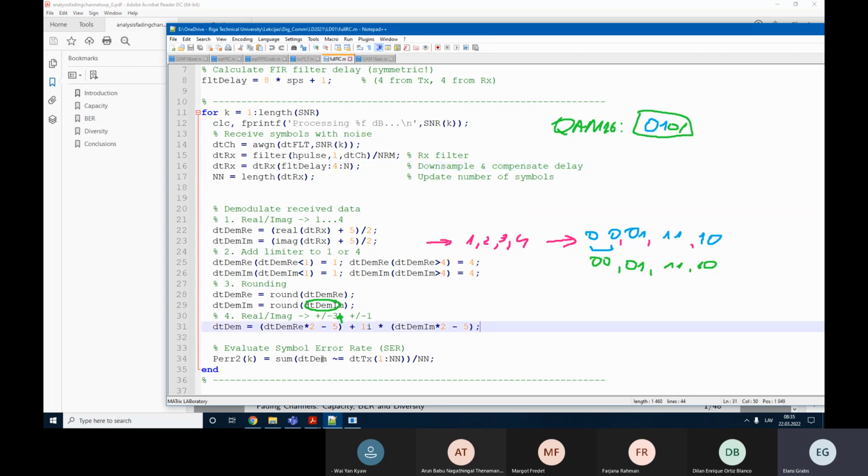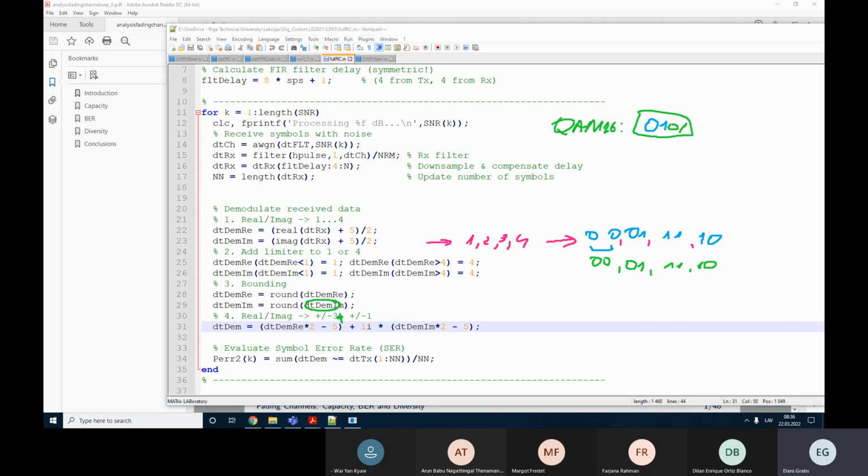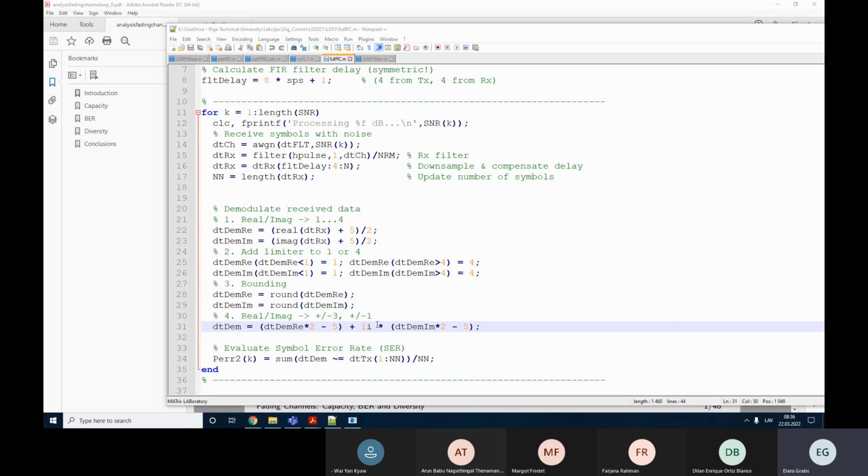We just look at the constellation map, read the signal, and also get some binary code. For example, let us say that something very terrible happened, and this demodulated symbol was received as 1111, which in total would produce 2-bit errors. And there was only one symbol error. So it's possible to recalculate just by making some modifications to this code.